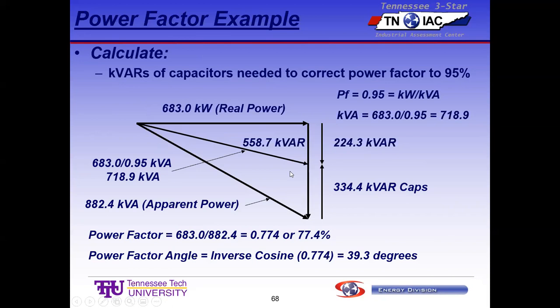So if you monitor this and you see how much it fluctuates over time, you might say, okay, I'm going to buy 50 kVAR increments. So what is that? 2, 4, 6, 7. It's going to have 7 50 kVAR increments with automatic switching. So then it has controls that monitor the power factor, and it switches the amount of capacitance in and out of the system so that it sets it between 0.95 and 1. Yeah. But that costs more.